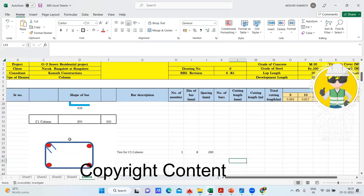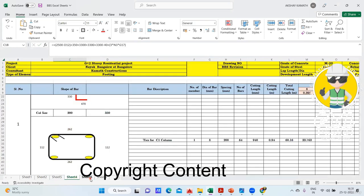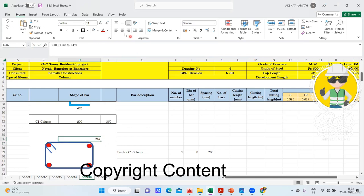So what you'll do, keep your mouse here, hit the enter button, open the bracket. So this is 350, no? 350 minus 40 mm from the left side, minus 40 from the right side, minus one stirrup, that is 8 mm, close the bracket. What we'll get? 262. Okay, you got 262 here also. I brought 262. Select this and bring it to the center and bring it to this. Okay, or bring it to the center.